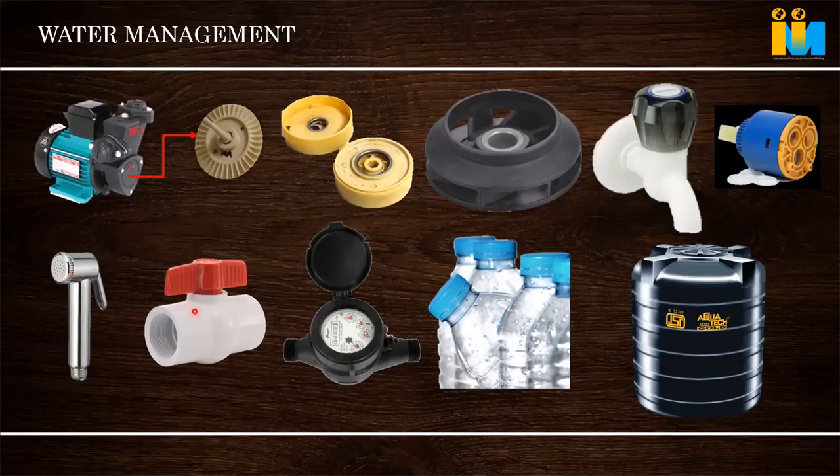And this is a valve, a heavy duty valve. Normally in this application the body is made of PVC. We have seen all pipes are normally made of PVC. Thick profiles can be made very easily, and it requires big gates in the mold. But it is a very good molecular weight material with very good strength. And when UV additive is added, it has very good weatherability also. We have seen our pipes staying in sunlight for years and years without any damage.